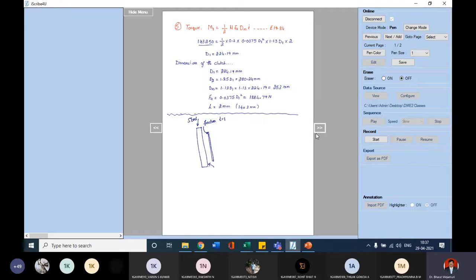But practically, if you take I is equal to 1 in this case, there will be only one effective surface. The problem will clearly mention that the effective surface is only 1. Usually, if you want effective power transmission, one more friction lining would be pasted here, so both the surfaces are effective. The clutch will go and engage here. In such cases you will be taking I is equal to 2. So by default, for single plate clutches you take the value of I equal to 2. For multiple plate clutches it will be many, which we'll solve later.